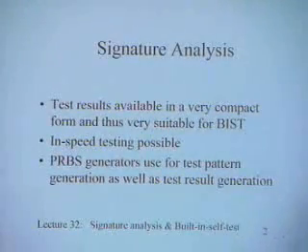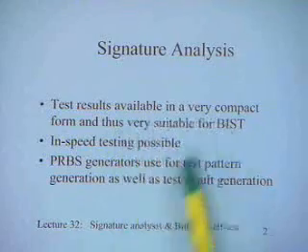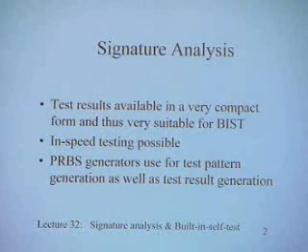This is based on the min term. Similarly, one can develop any type of signatures, but typically, for large functions, we do not want to apply all the possible test inputs, as that will increase testing time. So, what we do is we apply some random patterns, and we will see how these random patterns are applied and how the results are consolidated, the signatures are consolidated.